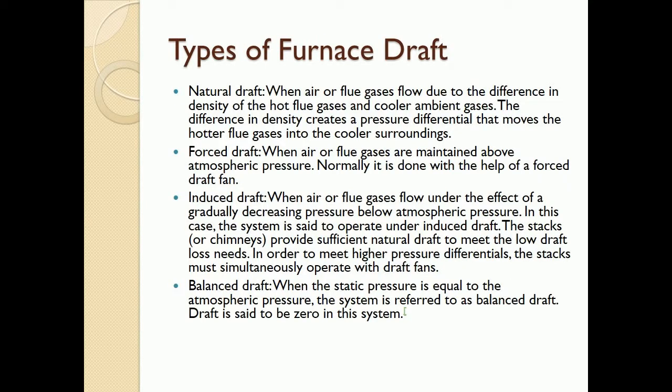Types of furnace draft are: 1. Natural draft, when air or flue gases flow due to the difference in density of the hot flue gases and cooler ambient gases. The difference in density creates a pressure differential that moves the hotter flue gases into the cooler surroundings. 2. Forced draft, when air or flue gases are maintained above atmospheric pressure. Normally it is done with the help of a forced draft fan.